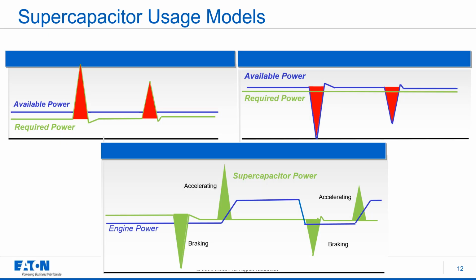All supercap applications fall into one of three use models. Peak power, where the main power source, whether it's utility power, a battery, fuel cell, etc., cannot provide the peak power needed. We see this often in devices with radio communications, where the rest of the device is very low power, except for the LTE or 5G radio. The supercapacitor provides power when data transmissions are needed.